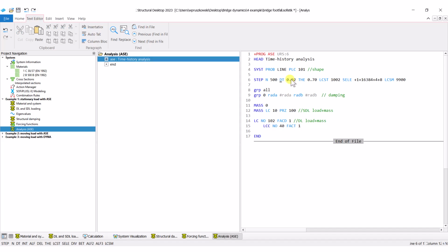Selecting an appropriate time step size is absolutely critical, and a balance needs to be struck here. Setting the time step as too large will not provide enough fidelity into structural response under dynamic loading. On the other hand, setting the time step as too small will unnecessarily overload SOFiSTiK with a sheer amount of calculations that do not bring that much to the table. Next up, we have a couple of settings that allow for a degree of control over the analytical method, load case numbering, and the results extent that is to be saved.